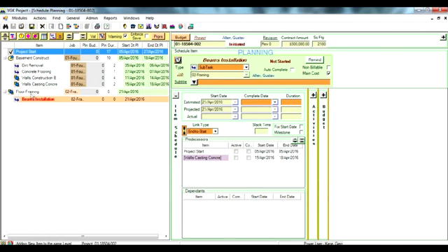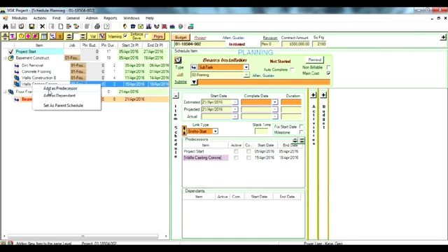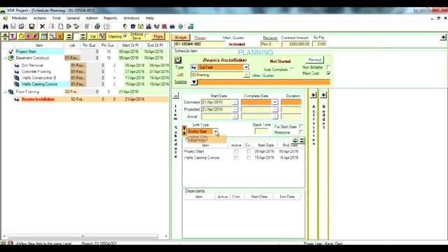Since floor framing is now the item's parent, it adds another predecessor to our item. This predecessor was not set, but it was inherited from our parent item. We want to add wall casting as a clear predecessor, and so to do this we'll just right click and choose Add as Predecessor from the menu. Now this predecessor is set explicitly. Again, we'll set an interval type with 2 days gap, and another item is added to the schedule.